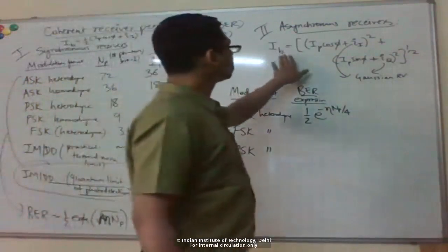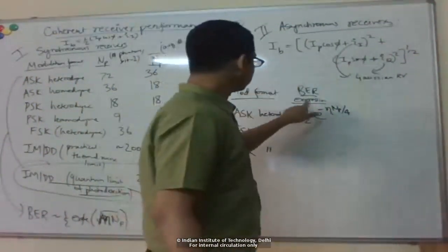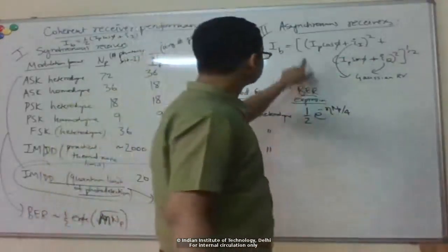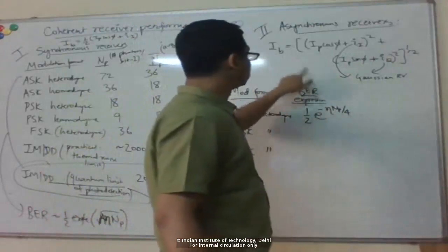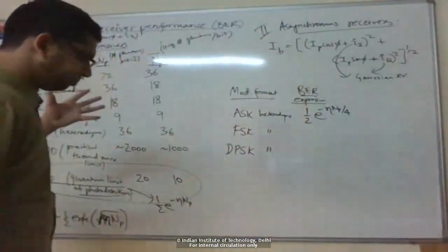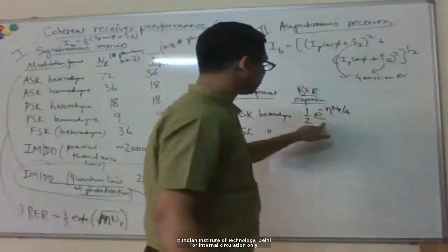So here, of course, it's not Poissonian; it's still some continuous distribution. But the final BER expression that we get comes out to be exponential. I think there are some approximations also involved because the integrals that you will get, I think, are not analytically solvable, and then you have to make some approximations to actually finally get to the exponential form.